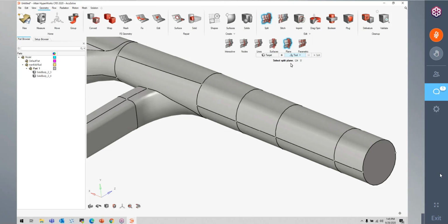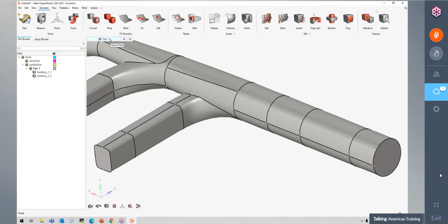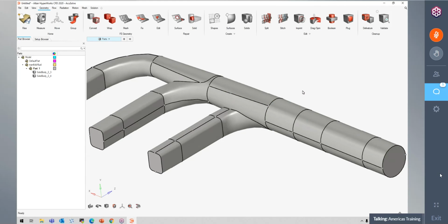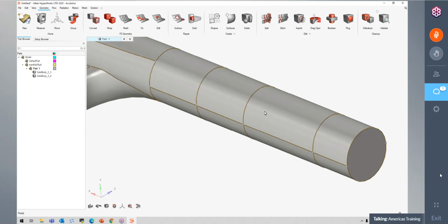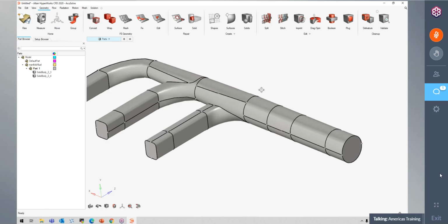So what I want to do now is exit this tool. If I press escape twice, you'll see that I'm out of the tool, and this little bar on the left here will pop up. What this bar on the left does, this is our selection tool. So this lets you choose what exactly you're trying to select. So let's say I want to grab only that section of the solid that I just cut off of this part, right? So I want to select these two separately.